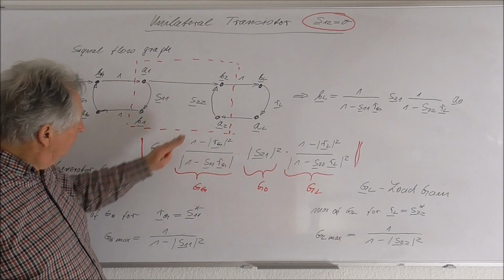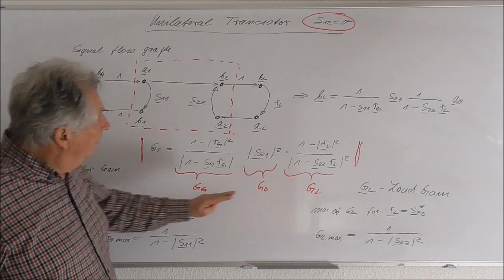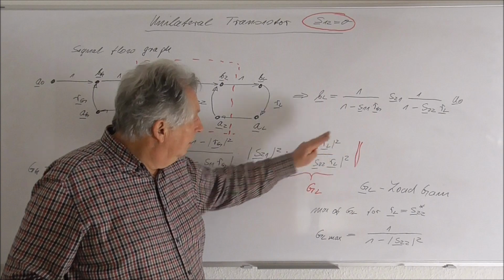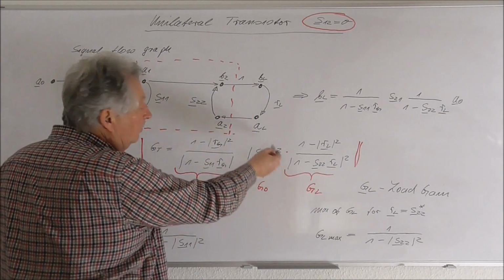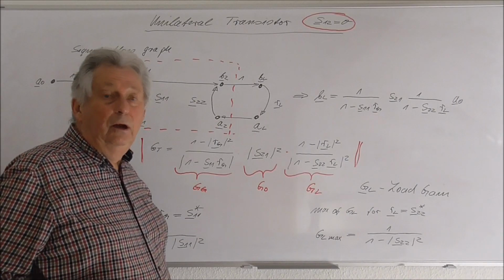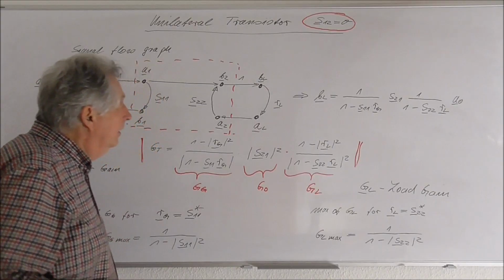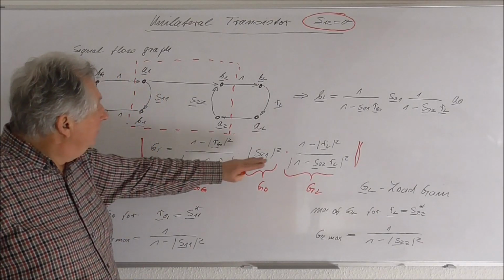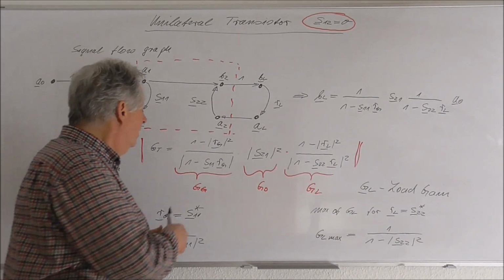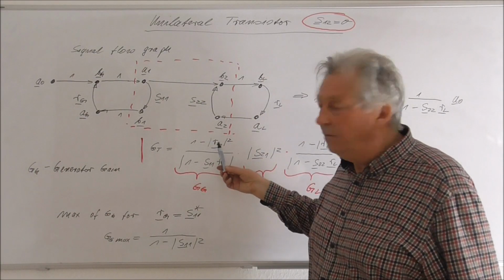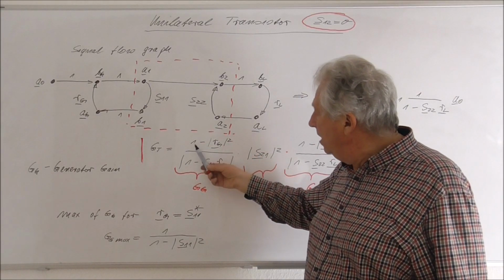One term, which we will call the generator gain, and one term we will call the so-called load gain. And of course G0 will describe now the influence of our active device. And now, since I have these three terms which are independent of each other, I can ask the question under which circumstances, for example, this term becomes a maximum.